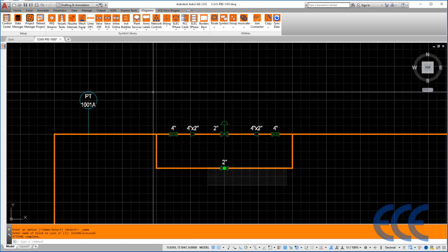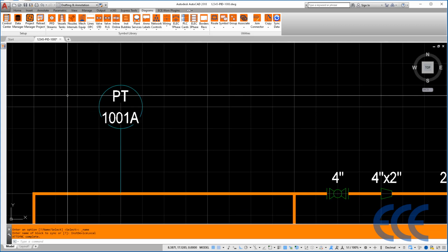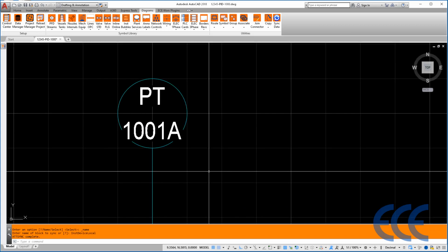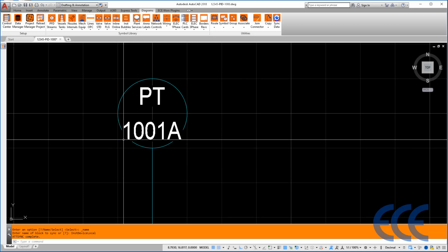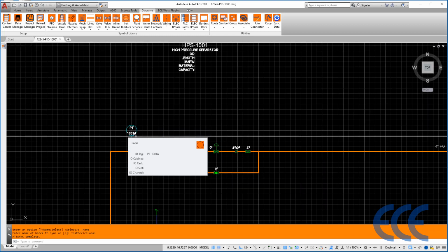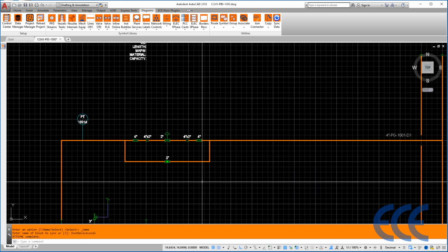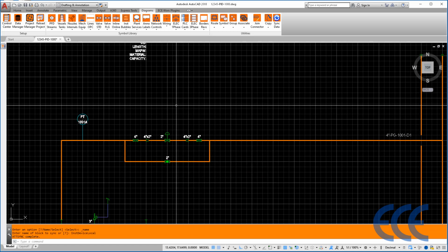Once I click OK, then that instrument bubble is going to fill with life. If I zoom in here, you'll notice some really nice properties of the ECE diagrams instrument bubbles. We are automatically breaking the bubble when the text string is going to extend into it. So this is really nice where we don't have to worry about breaking interfering lines. Let me go ahead and focus on the control valve now and get that current to pneumatic converter on there.